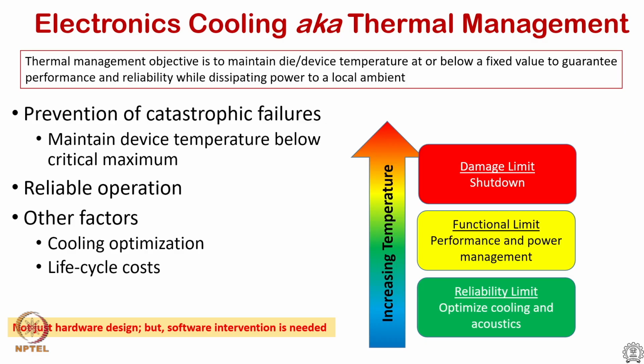Essentially, the speed is reduced by 1/3, so instead of operating at 1 gigahertz, you go down to 2/3 of a gigahertz. Something like that is done to reduce power, because we will see shortly that this switching frequency or speed is directly related to the power dissipated by these devices.